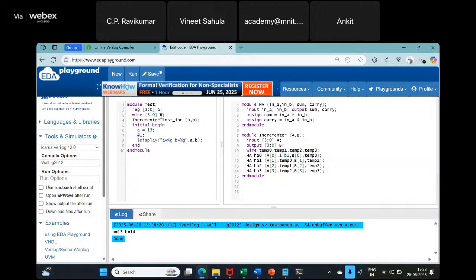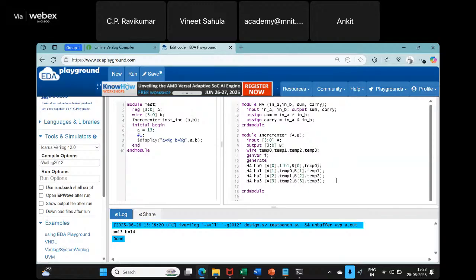But suddenly, if I decide that all of them must be 15 colon 0 or something like that, it will be too much work. That is where generate helps. So we can write a generate statement, right? And say genvar I, and generate.